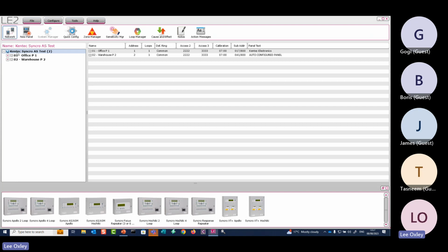So you've learned the panel. Your network cabling goes round panel 1 and 2, so you've extended the network cabling. It now goes out of panel 1 into panel 2, out of panel 2 into your new panel 3, and then out of panel 3 back to panel 1 to close the loop back up. The panel's powered up as panel 3. Now the other two panels are going to be in fault because they don't know about panel 3, so it's going to say unexpected network node. Panel 3 will be in fault because it doesn't know about panels 1 and 2.